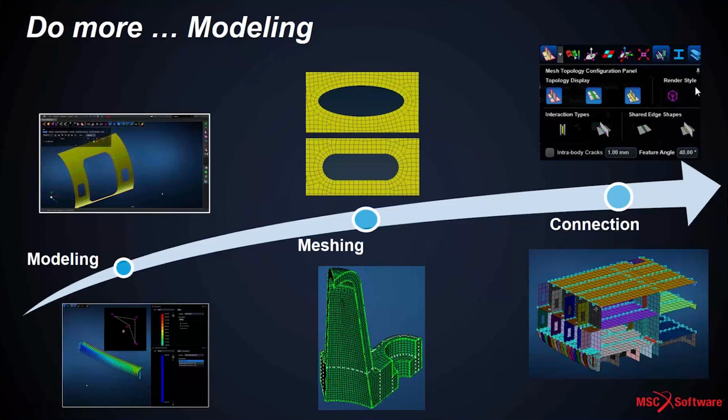Plus, when the holes are close to each other, or when the holes are close to the boundary, we are giving the treatment to the meshing so that it takes care of the quality of the mesh and creates good quality elements around those holes and the washers and also close to the boundaries. Likewise, there are enhancements in the connections, in particular the tie connections. Since Apex is targeted for large fabricated structure simulation, we are introducing enhancements in the usability and what is called the topology visualizations.